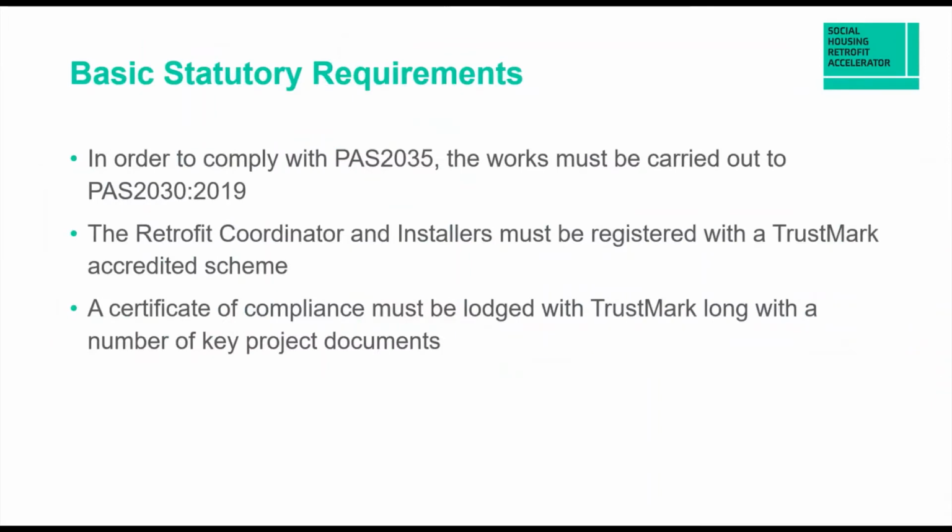So the basic statutory requirements, which you need to really be quite aware of, is in order to comply with PAS 2035, the works must be carried out to PAS 2030-2019. So 2030-2019 defines how each individual measure needs to be designed or installed. PAS 2035 just defines the overall project management process.